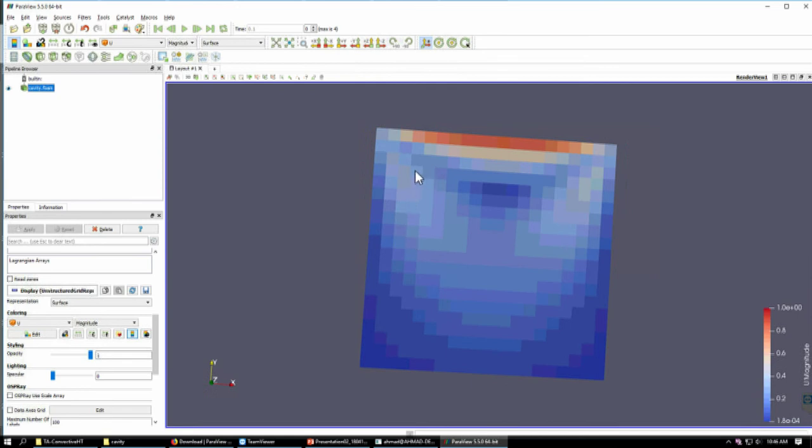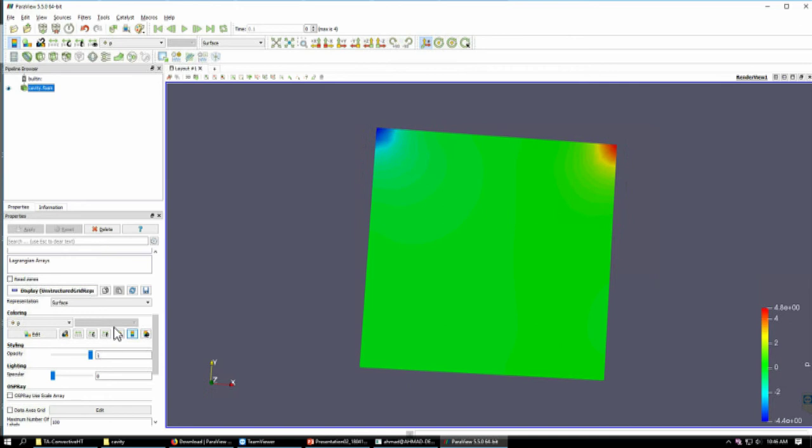You can see that now the display is sort of distorted because each cell has single values. So what is the other option doing? This option is basically interpolating between your results. It is just interpolating the pressure between the cells and giving you a continuous gradient. So it is not solving further. It is just taking your existing results and showing an interpolation of those results.